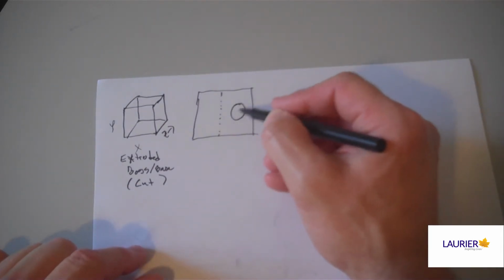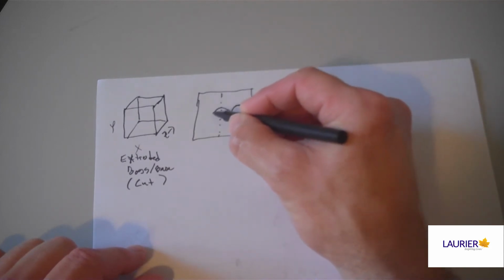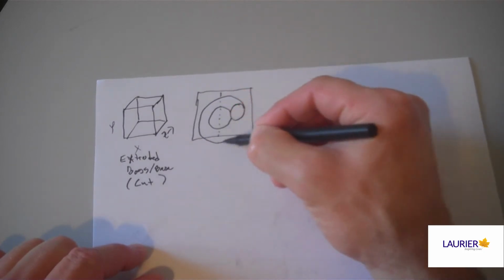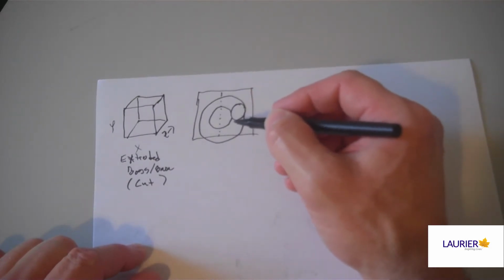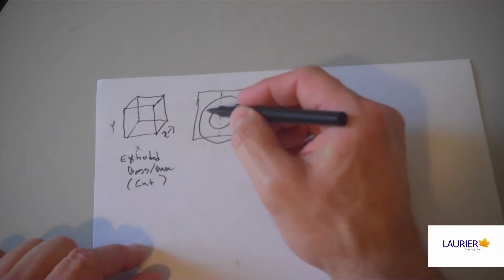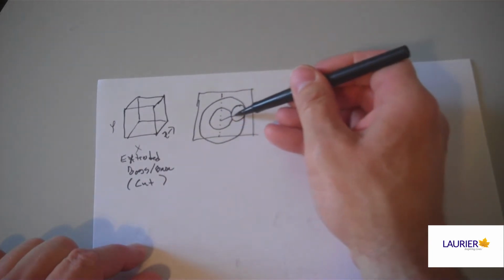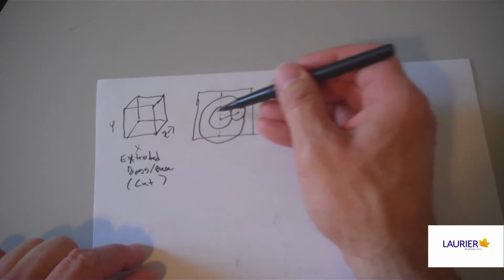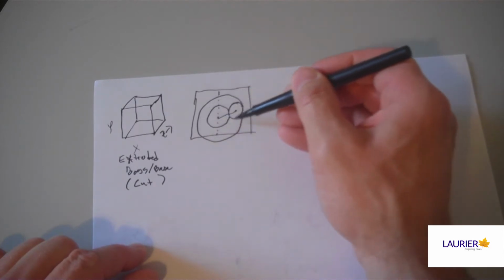To make this into a solid, what we're going to do is swing it around the axis as though it's a tetherball. And like the baseball bat example a little earlier, every bit of volume that the tetherball would displace while revolving around the axis becomes part of the solid. In other words, where you don't want your head to be when the opponent serves the tetherball is where the solid, or cut, if it's a removable material, will appear. The contour will always stay the same distance from the axis, and we can choose how many degrees it travels through this arc. A 360-degree rotation through the arc would produce a round contour that creates my favorite shape, the donut.